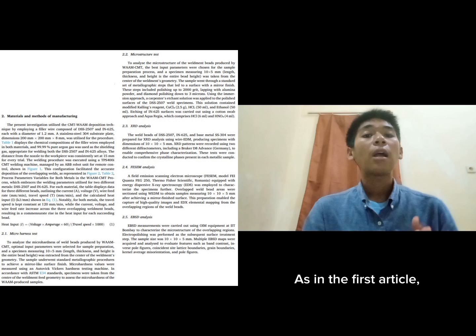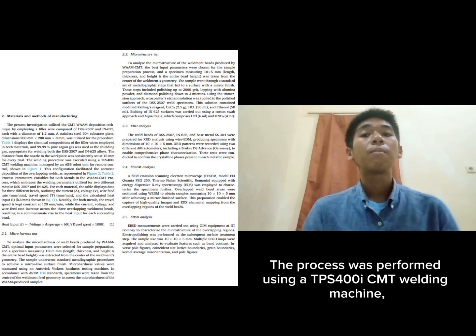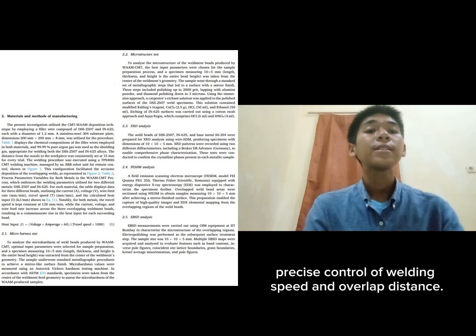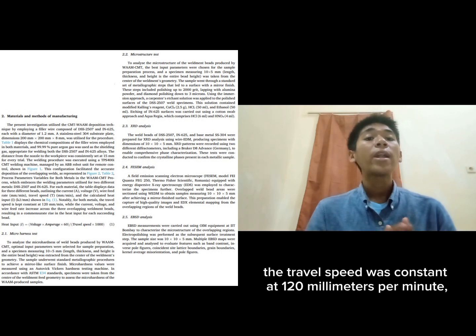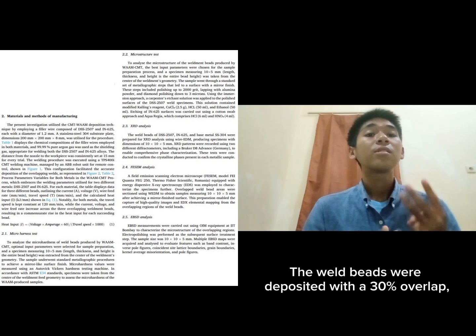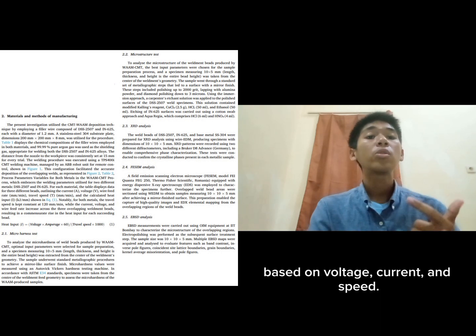As in the first article, argon gas with 99.99 purity was used as the shielding gas. The process was performed using a TPS 400i CMT welding machine, which was robotically controlled by an ABB arm. The setup allowed precise control of welding speed and overlap distance. In this experiment, the travel speed was constant at 120 mm per minute, while the current was varied at 140, 160, and 180 amperes. The weld beads were deposited with a 30% overlap, and the heat input was calculated using a standard equation based on voltage, current, and speed.